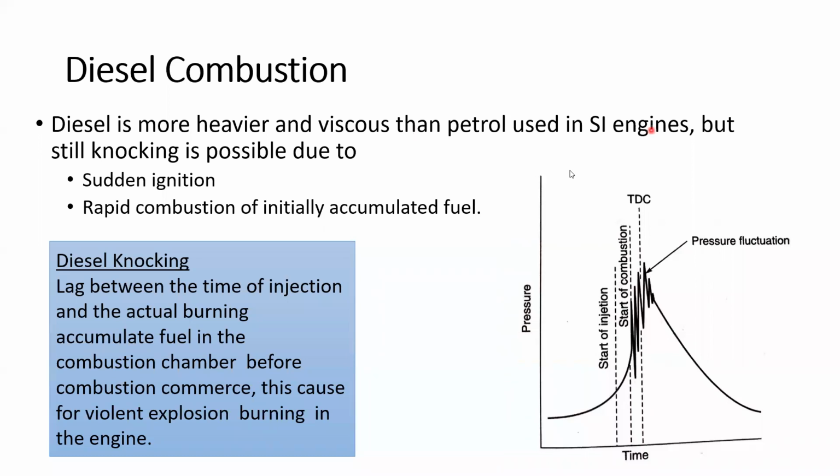So yeah, if it is a modern vehicle and the engine starts to knock, the vehicle tries to fix it itself, because there's something called a knock sensor, which measures if knocking is happening inside the engine. If that is not the case, if it is an older vehicle like a carbureted one, the engine cannot measure that.